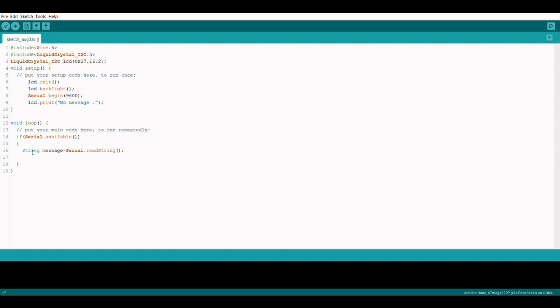and we can actually just display it on the LCD module. We have written no message here, so we'll first clear that with lcd.clear and lcd.print the message, and let's go to the next line by using lcd.setCursor. So lcd.setCursor at 0, 1, and let's print the message. lcd.print message. Let's just add a time delay of a few milliseconds for each loop, delay 10. So this is basically the code which I have used in Arduino.